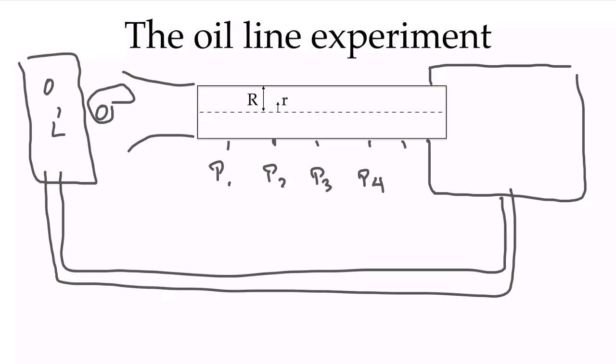In so doing that, we can see how long it takes to develop, because if the pressure difference is linear, we have the fully developed solution. If it's larger than linear, if the pressure drop between pressure taps is decreasing, we see that the flow is still developing. And there's one more feature that we put in this.